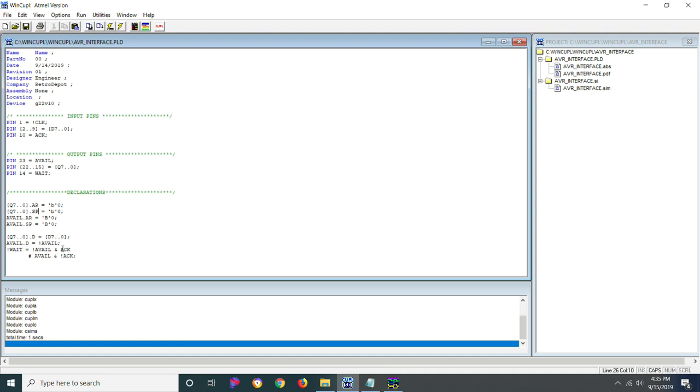You have to play with it. You have to double check your code. It can get a little bit confusing because it's much unlike any other code that you're doing. Unlike Verilog or VHDL, where you have certain things that you're assigning, with this you're just writing logic equations is all that you're doing, and the compiler is basically flipping those fuses on or off. So that's it for this.